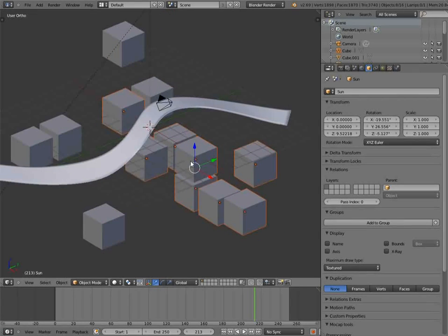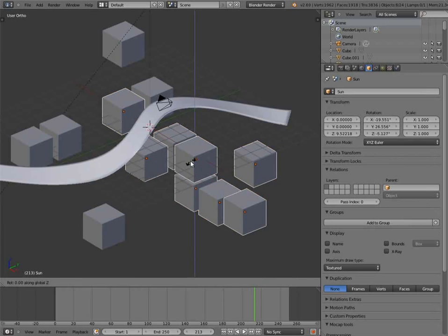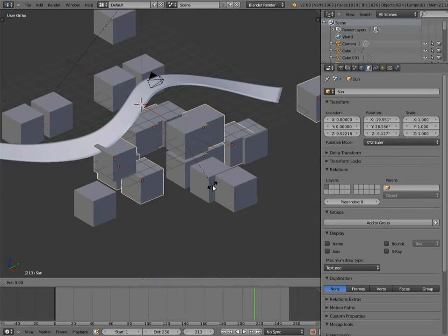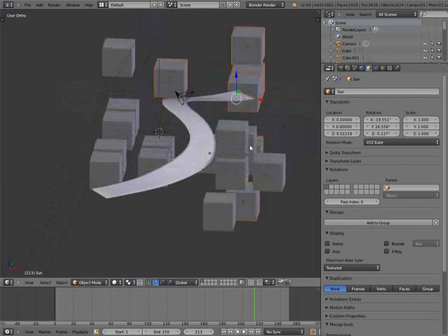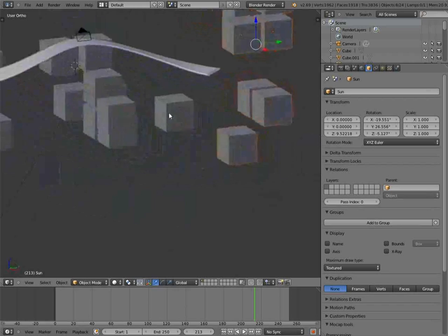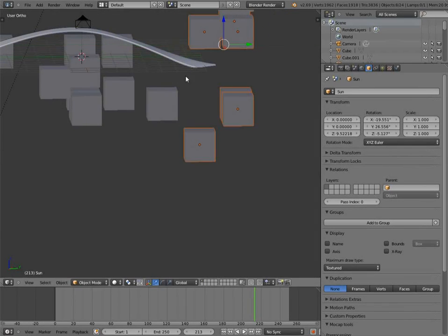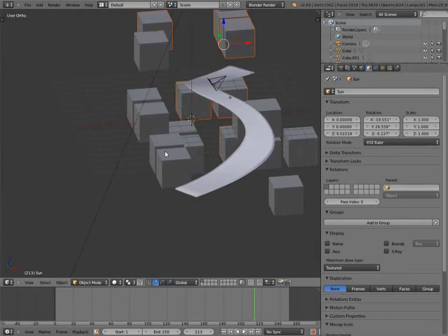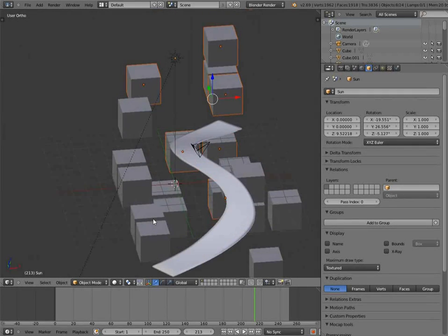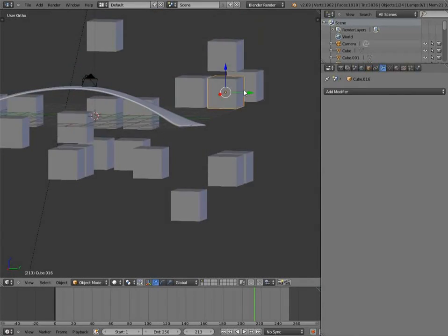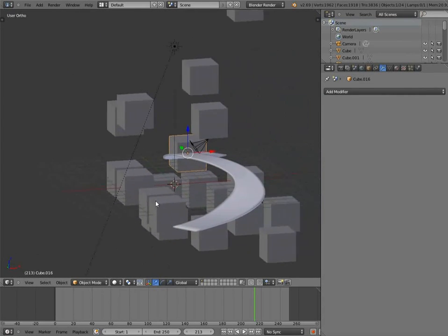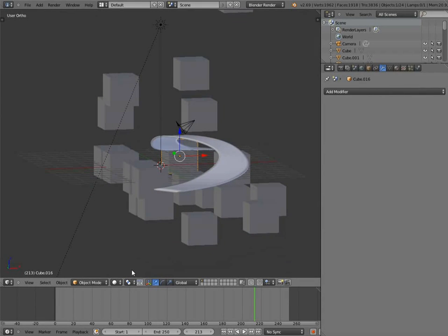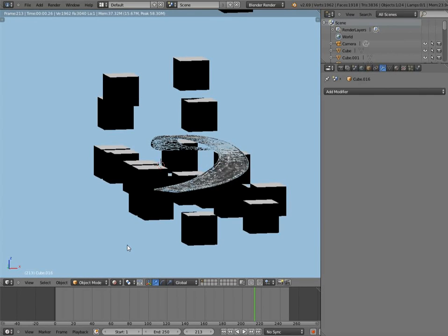Deselect the sun. Okay, duplicate that, rotate it along the z-axis and along the x-axis so we can have some height. Along the z, about there, a little bit forward. And there we have it. There's a view, right there. Let's just move a cube so we have something at the end of the image, about there. Okay, now if you save it again and you go into rendered view, there you go.